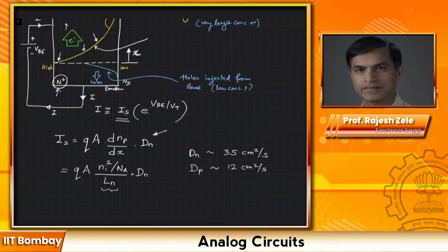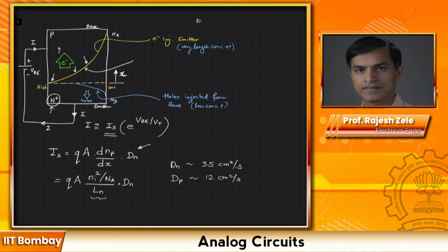In the previous lecture, we just used it as a formula, but I just wanted to give a little more insight into what's really going on, specifically this exponential decay of the carriers in the lightly doped region. We would like to add the third electrode, which is the collector, and see how things change. This profile changes when we add the collector, the third electrode.